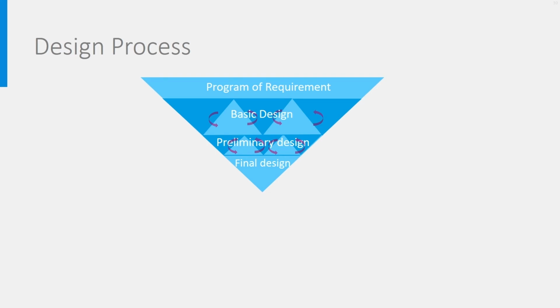Let's look now at the design process. Well, any design starts with a program of requirement. In the past, the usage was that the program of requirement was made by the client and the architect, telling the HVAC designer what he should use. Double glazing, for instance, and a heat pump, or a chiller from a certain brand. This is well possible when HVAC equipment is relatively simple, but in larger buildings, and when aiming at sustainability, it cannot be done like that.